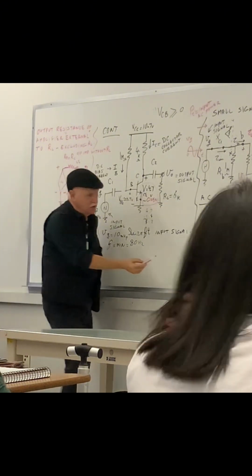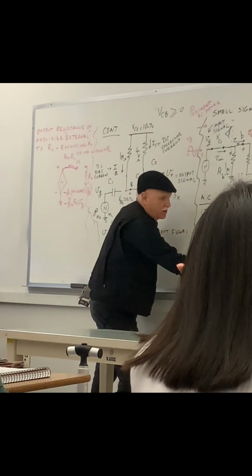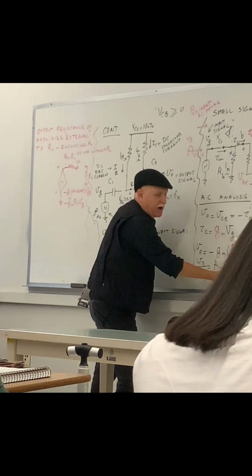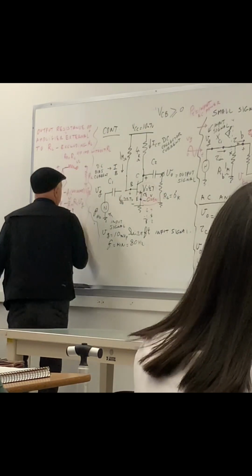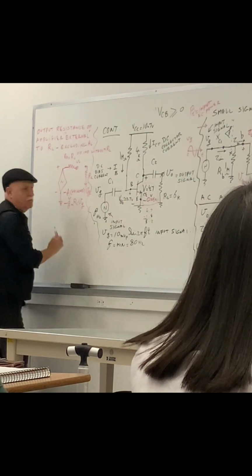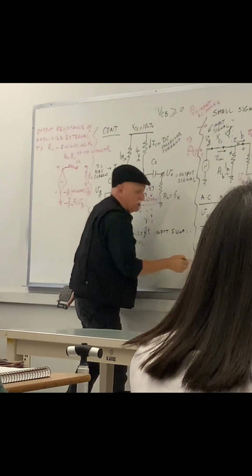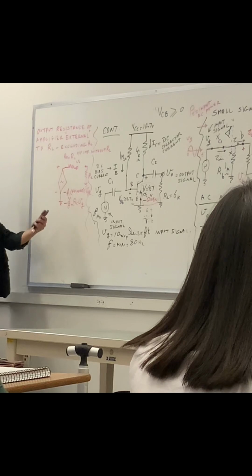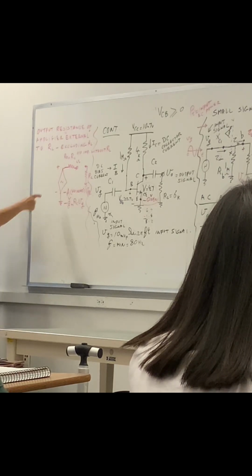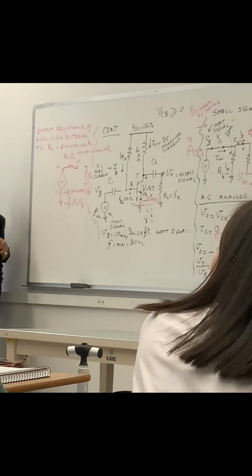So what it is, RL is infinity. Infinity parallel to RC is just RC. So RC GM, that's what you have. RC GM multiplying VG. That's your internal Thevenin source, amplifier presented as a Thevenin source. And that's the node VO.